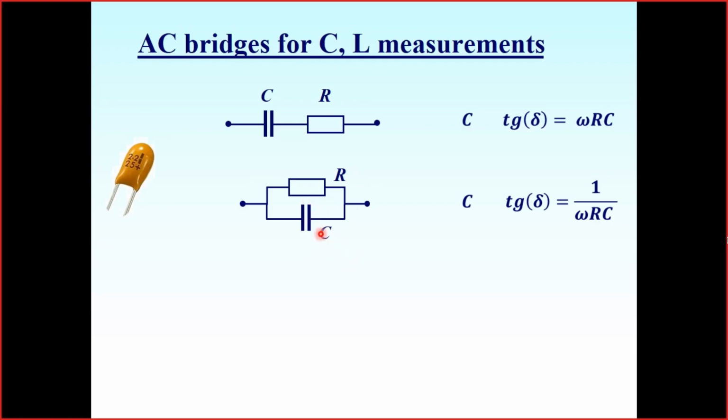So we may easily interpret what the capacity means. It's the real capacitance of the capacitor, and what does R mean? This resistance is actually the leakage resistance. Maybe it's not the dielectric in the capacitor that is responsible for such a behavior. It may be the moisture film, which always at room temperature is around any object, and some current flows through this moisture. Never mind. So this is the idea of this parallel connection of the capacitor and resistance.